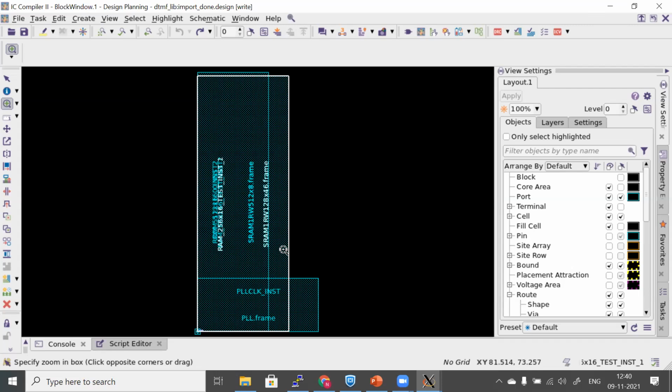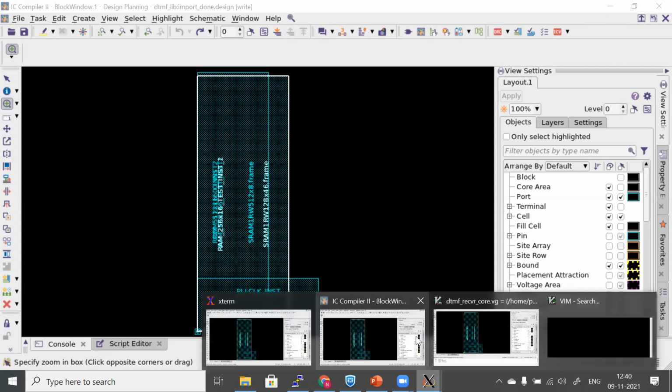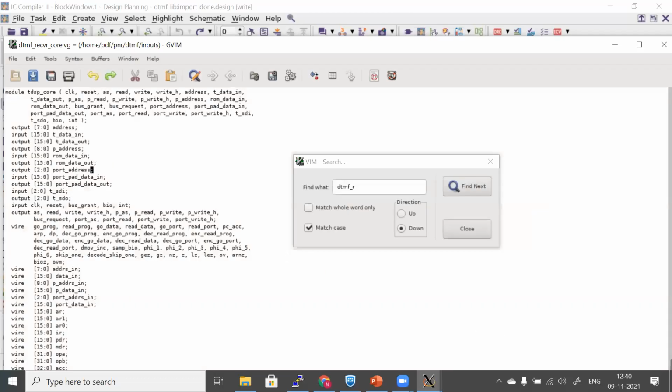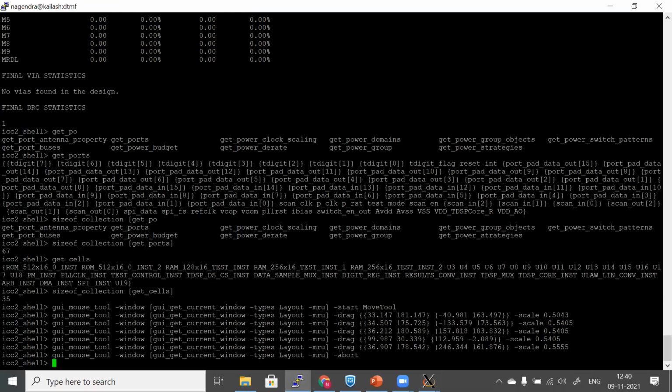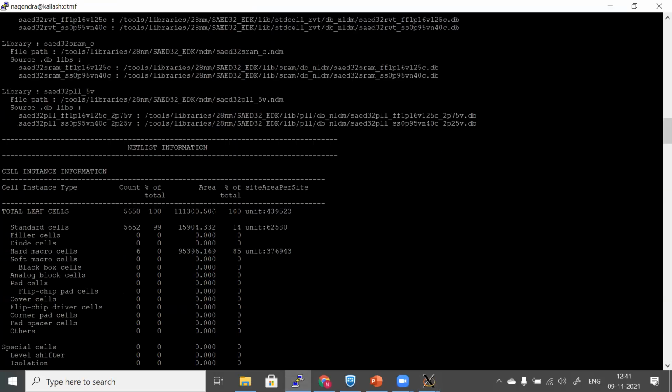And blockages also. Right now, you don't know what blockages are; we'll see it later. But depending upon macros, so macros plus standard cells, you can see the area of macros and standard cells. What is the area of macros and standard cells? We have seen that somewhere, right? What is that? You can see this, the total area. This is the total area of your cells. So depending upon that, you need to design your core. Okay? Getting things? Yes, sir.